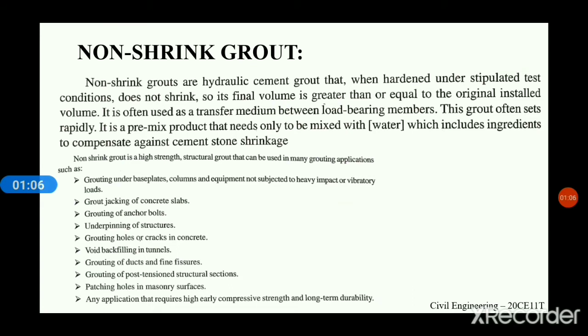This slurry can be self-flowing, and the grouting material can automatically infuse narrow gaps under shock-free conditions, adapting to pouring and grouting such as complex structures, dense reinforcement, and narrow spaces.